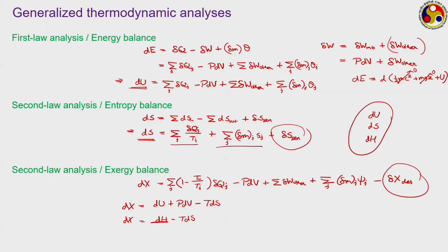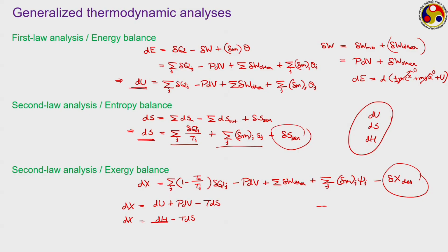So, in common thermodynamics we generally can classify properties in two different manners. Of course, one type of classification is intensive and extensive, but here we are talking about the practical sense. A group of parameters like temperature, pressure, specific volume, mass, etc. can be measured very easily, whereas parameters like internal energy, enthalpy, entropy, etc. can't be measured directly.